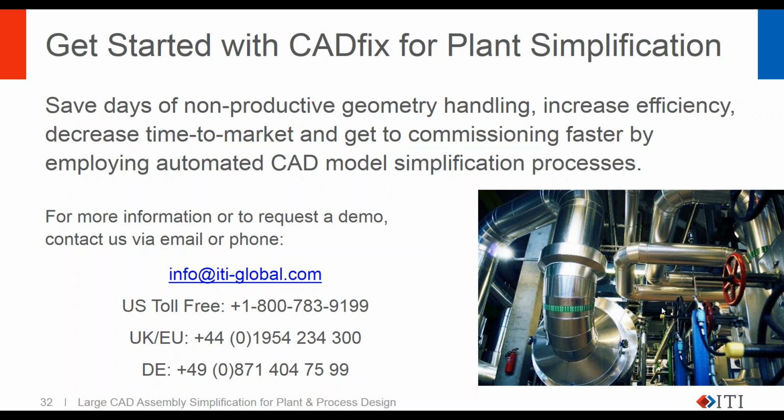First question, do I have to perform the simplification again after an update of the assembly geometry, or is there an automated possibility? You can run it automatically in that the wizard process is automated. If you work from the assembly structure, we can capture changes that you make to that assembly structure and replay those.